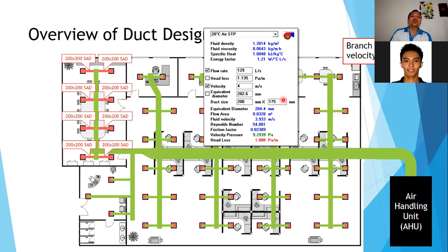If you are selecting ducts, please do not select ducts based on integers other than multiples of 50 and 100. Do not size ducts at weird dimensions like this 175. Nobody will do 175 for you. Either you do 150 or 200.